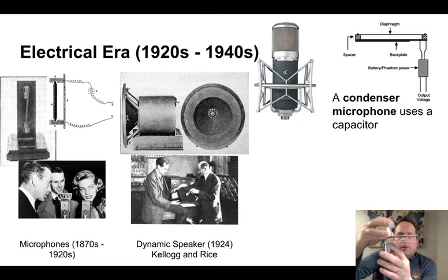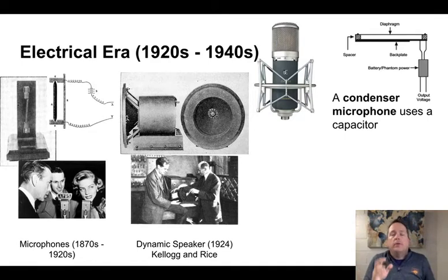If I have this parallel plate capacitor and a sound wave makes the top plate jiggle, if I've previously charged up this capacitor, that jiggling in position between the plates of the capacitor will actually make the potential difference, the voltage between those two plates, oscillate and form an electrical wave that mirrors the properties of the sound wave that created it in the first place. So you are converting a sound wave in air particles into a voltage wave.